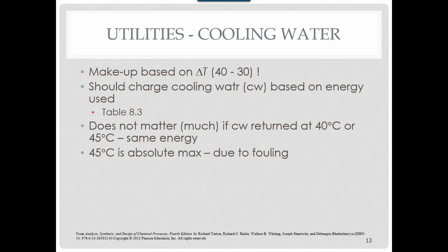If the cooling water is being returned at 40 degrees or 45 degrees, it's not just that big a difference, okay? Just kind of treat it as all the same kind of cost. When you're doing estimates for how cooling water is used, when it's being used to cool a process, the maximum exit temperature for your cooling water ought to be 45 degrees C.